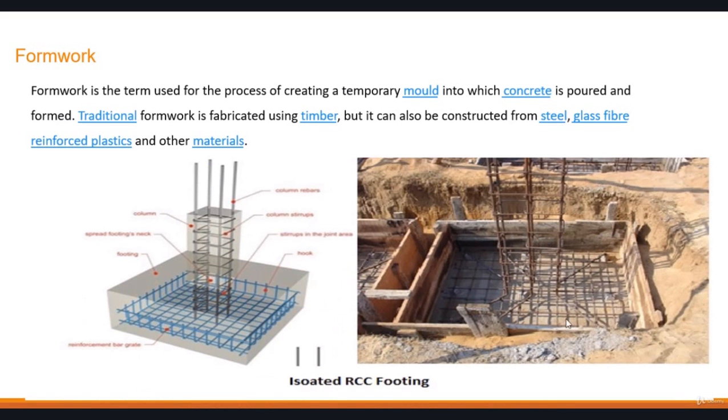Here you can see we have just isolated foundation, and this is the formwork for isolated foundation. Remember that the quantity of the formwork will be in meter square or feet square. For example, if you are finding the quantity in feet, you have to find it in feet square, and in meter the quantity will be in meter square.